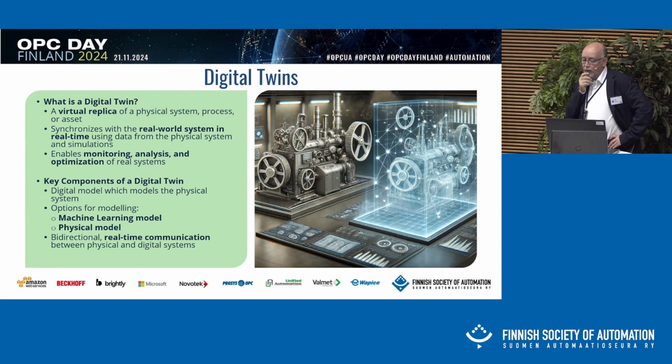You can use the FMU to find out beforehand, if you run it in parallel with the real system, what happens if you change process parameters in different ways, so you can see what will happen before you make the change in the real running system.